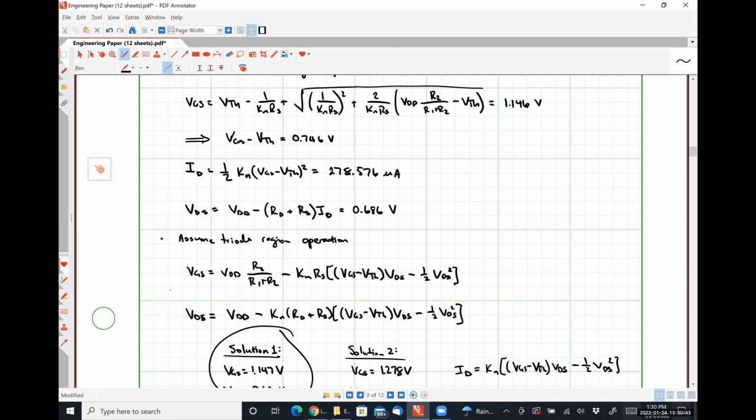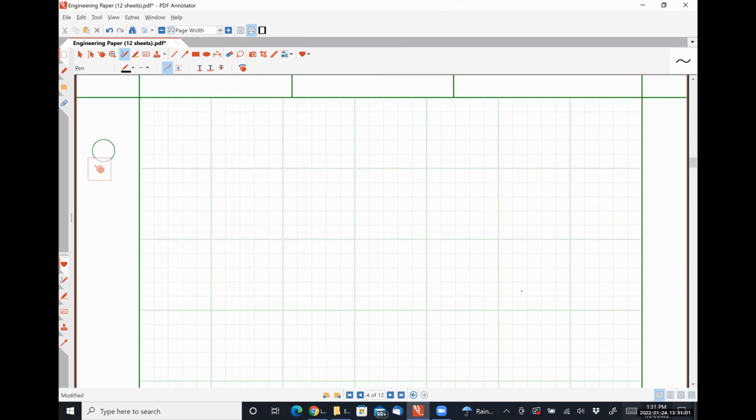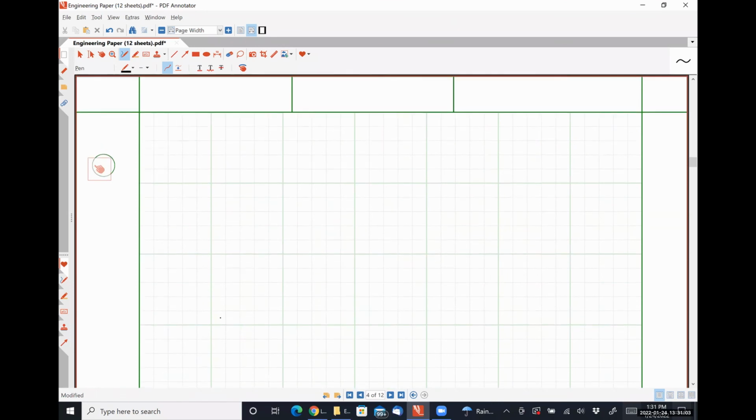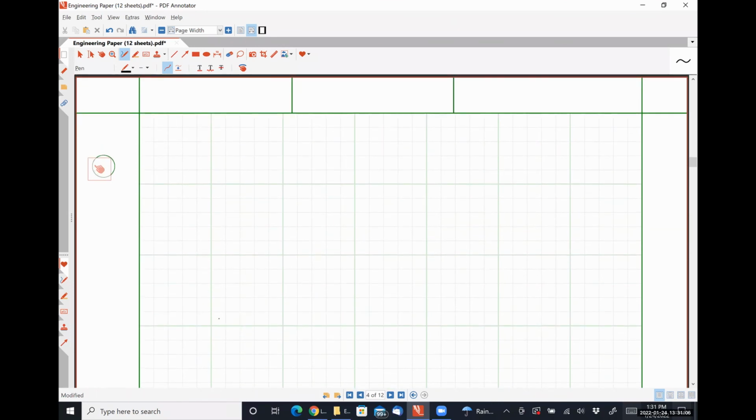So let's look at this same circuit again, not this numerical circuit, but the same circuit again. Our 4 resistor bias network with channel length modulation included, since we know that we probably want to bias this guy at a point that isn't at the edge of saturation. Now, truthfully, a lot of textbooks will tell you, ignore channel length modulation when you're doing the DC bias point stuff, and then include channel length modulation when you're doing your small signal analysis, which we're going to be getting to pretty soon.